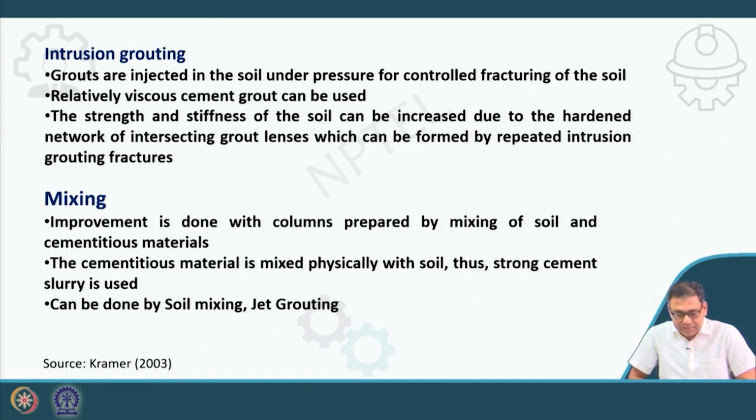The strength and stiffness of the soil can be increased due to the hardened network of these intersecting grout lenses, which can be formed by repeated intrusion grouting fractures. So that means controlled fracturing is done in the soil, and the strength and stiffness of the soil can be increased. How is it increased? Because we are applying this relatively viscous cement grout under pressure, and then we are doing this fracturing.